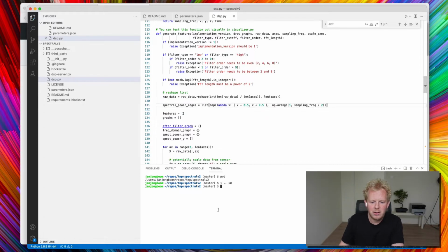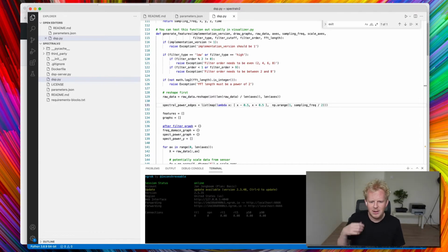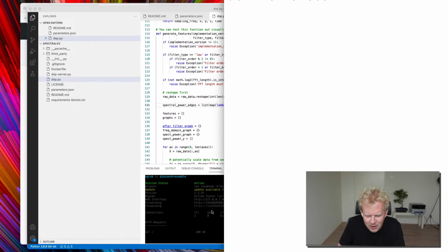So to start this block, I can say start the DSP server. That runs on my computer as a web server. If you are an enterprise customer of Edge Impulse, you can push this to your organization and we host it for you. Then in a second tab, I'm going to run ngrok. ngrok is a reverse proxy that makes this block available over the internet. Here is my forwarding address, and I copy that.